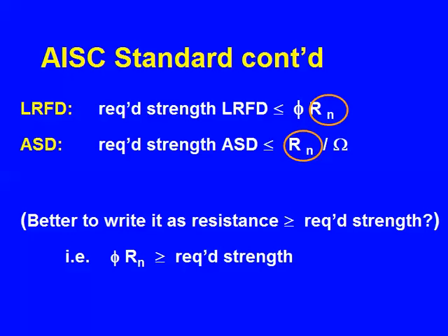So regardless of which system you're working in, you're going to calculate, whether you know it or not, and now you do know it, the resistance of a bolt in shear. And then you're going to use it in either allowable stress design or LRFD. So you are at this stage in the United States, where the two systems do have a linkage, and it's a legitimate way of doing it.